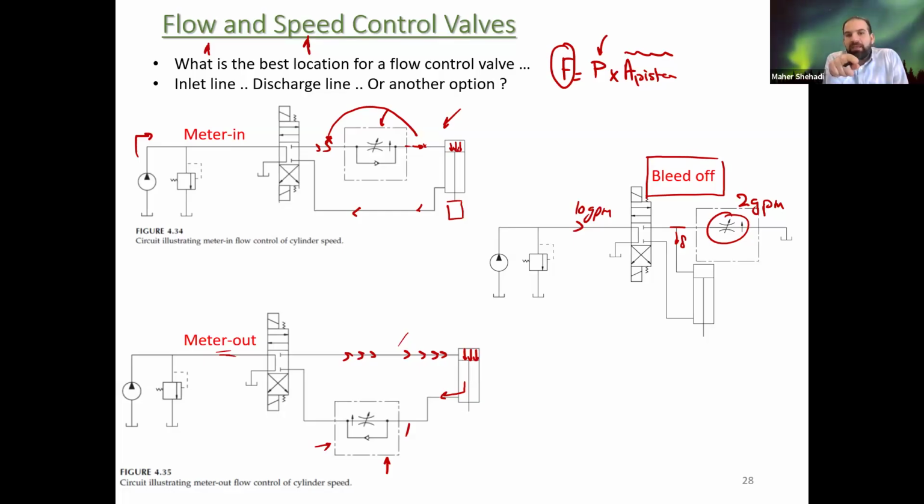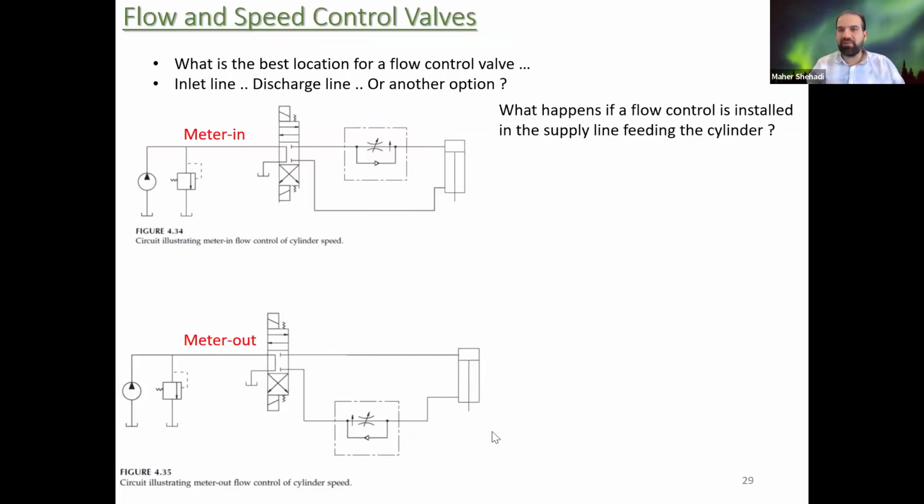So again, it depends on the application. If you're pushing, let's say this cycle is just pushing boxes, so it goes empty in the retract, we don't care about the force for the retract. But if it has a load that's pushing back in both ways, extension and retract, then it does matter which one is more critical. If both are critical, then probably I should go to the bleed off. And that's why we have the bleed off. I think that's what you have on this slide.